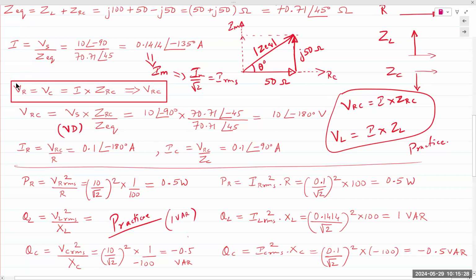Yes. So it doesn't really matter what component it is. In the end, we treat it like all resistors, whether in series or whether in parallel. The only difference is instead of simple numbers, we now have complex numbers.